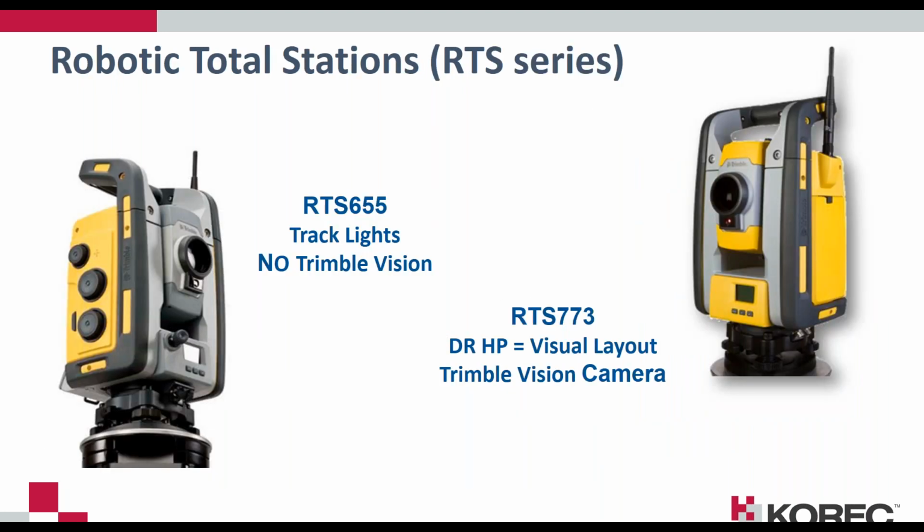The robotic side of things, so we have here 4 robotic total stations within the portfolio. So we'll start out with the RTS 655. It's a 5-second instrument. Now this, for me, is really the workhorse if you're in the construction environment. It doesn't have the Trimble Vision loaded on board, but it has the Trimble Tracklight capability, so it allows you to line yourself up in the true line of where your point needs to be staked out. So it makes that process quite quicker for you. Again, with all the Trimble products within the portfolio, it comes with the standard benefits of the Trimble MagDrive there as well.